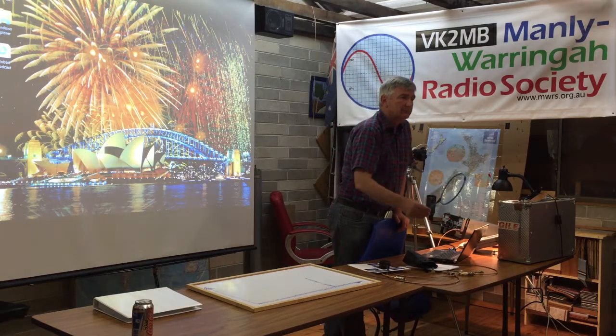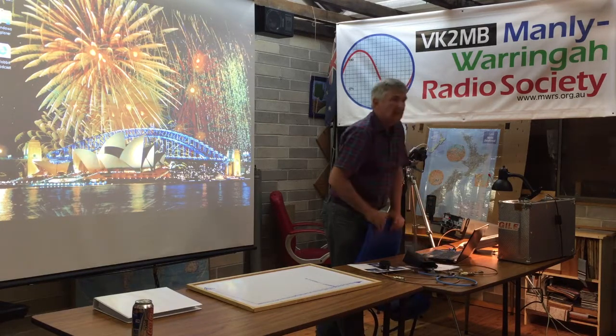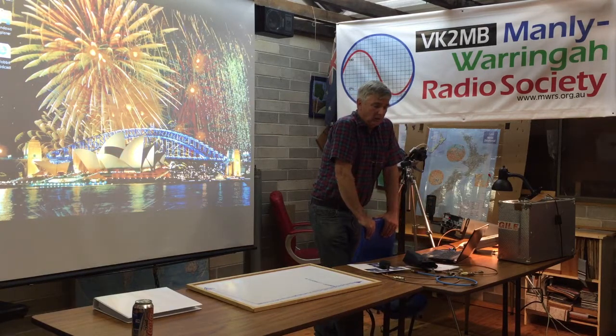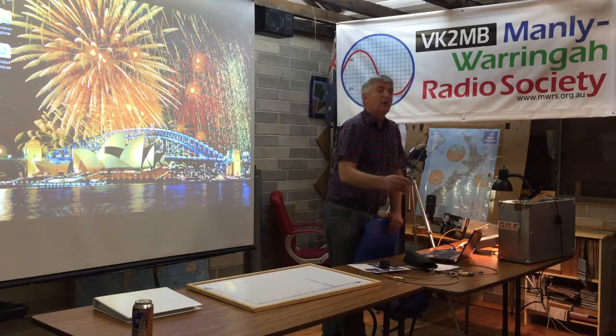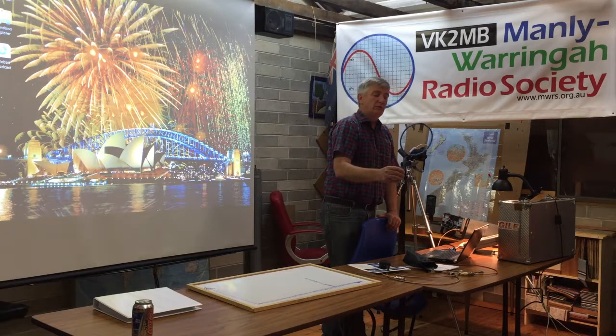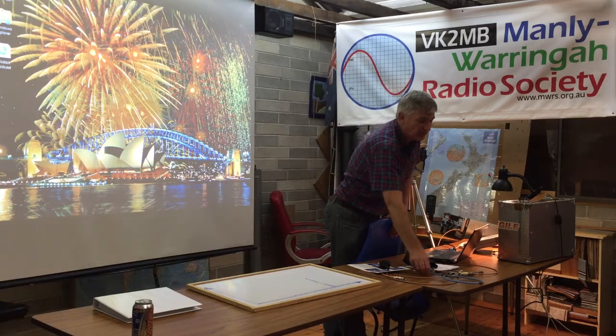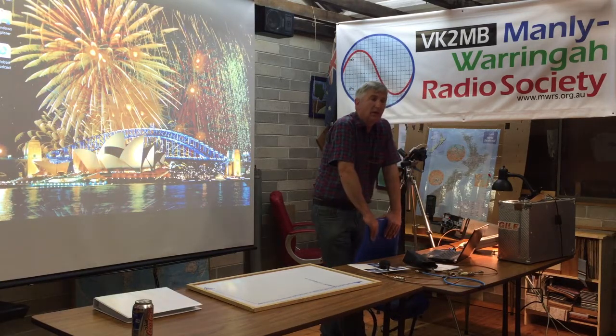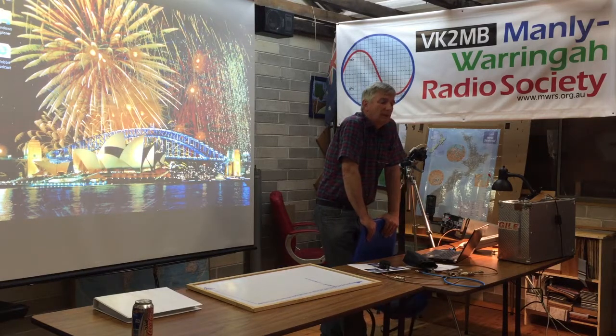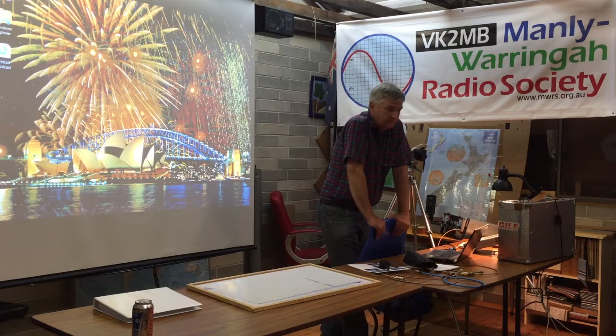So does that plug into the spectrum analyzer? Yes. Is it fair to say that it only works really in the near field? Oh, yes, more or less. It's quite insensitive, so you have to be close, which is good. You don't want a sensitive, amplified antenna when you try to hunt down noise, typically. As you know from things like fox hunting, that's in fact one of the problems: when you're close, you get too much signal, and it's hard to find.